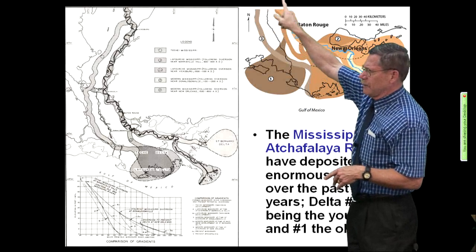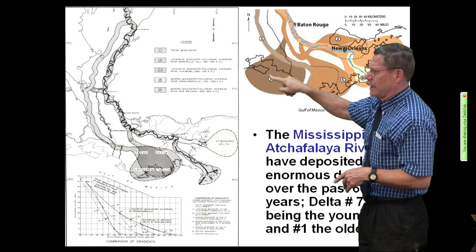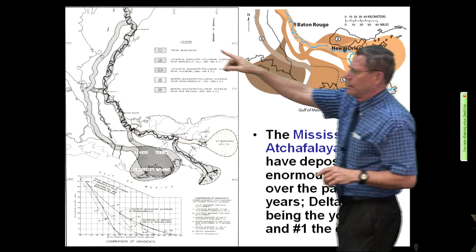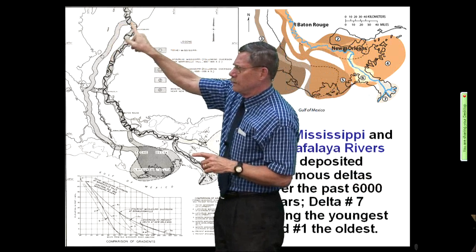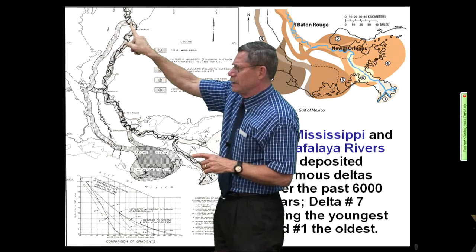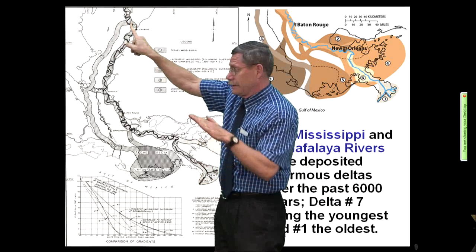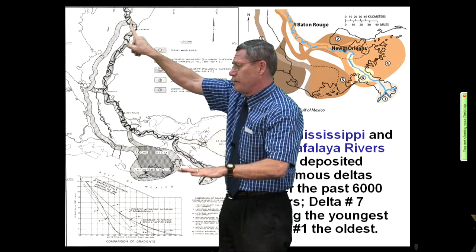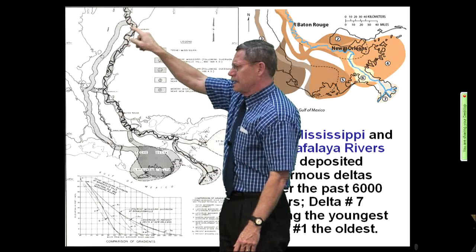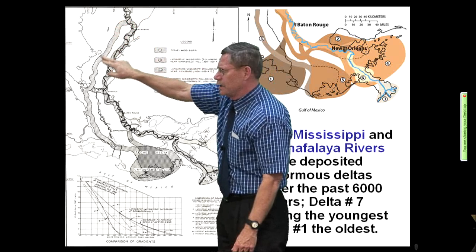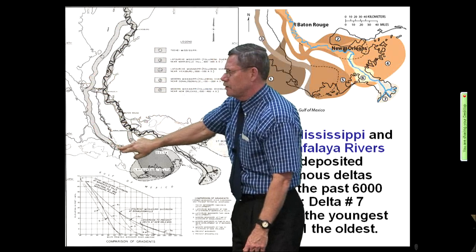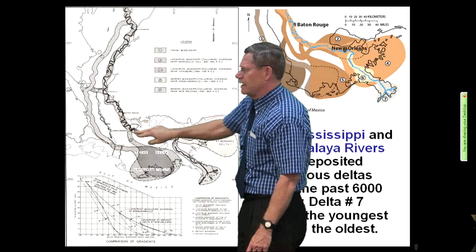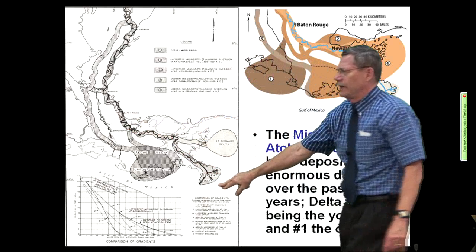So if the river ever breaks out up here and comes down the Atchafalaya, it's going to cut one heck of a canyon in a couple hours. 24 hours, all going to be over. And all the water is going to come out of there. That's called the Old River Control Structure. And it did fail in 1973, but they didn't have a catastrophic failure. They had an undercutting of the hydraulic control structure, but they didn't lose it because it was on battered piles. And so they built a new one there next to it. They more than doubled the capacity, but the river would cut this thing in a flash because that's a shorter distance to the Gulf, right down here. Boom. It's 1/3 the distance of taking the current route, which is very serpentine, all the way out here.